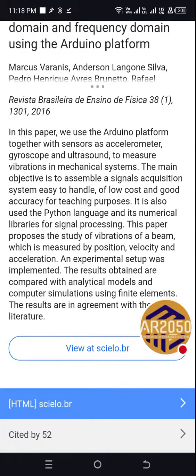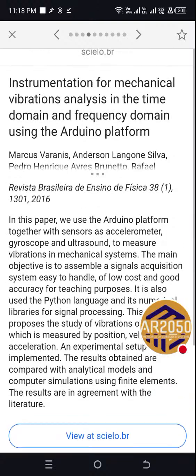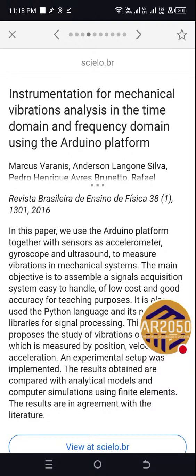They added a lot of sensors. You don't have to do all of them. Just pick one, implement. MPU do good with the vibrations, if you ask me. So we can use the MPU and place them on some vibrating surface. Maybe if you have a pedestal fan, just put the MPU on the surface of the motor.